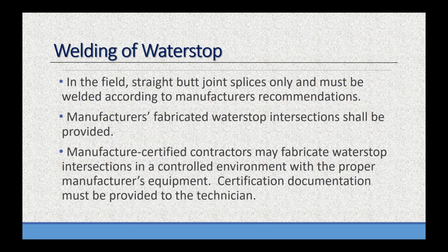Welding a water stop. Again, there's no major change here other than the fact we're dealing with a thicker, beefier water stop that's going to be a little bit more difficult to do. Welding a water stop in the field, straight butt joint splices only, and must be welded according to manufacturer's recommendations. Manufacturer is going to tell us how we're going to manipulate their product, and we need to follow it. Manufacturer's fabricated water stop intersections shall be provided. In other words, we're looking for those preformed L's. We're looking for those preformed T's, very similar to what we've done in years in the past.